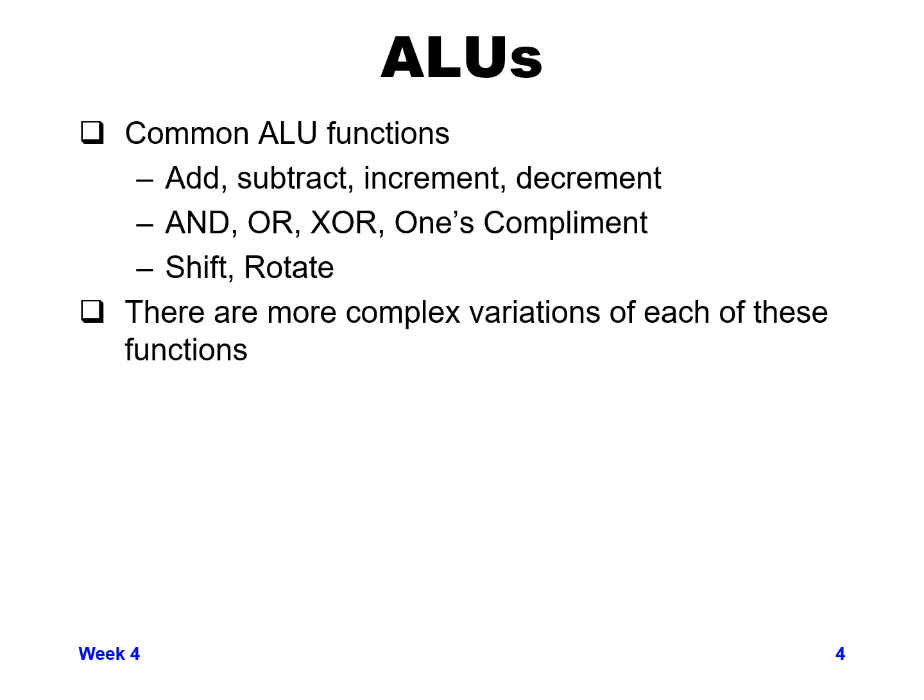And then there's other functions like shift and rotate, where you will take either the value of A or B and shift all the bits left or right, or basically rotate it around. So with a shift, you'll shift in a value either on the left or right, depending on if you're shifting left or right. With a rotate, you would take the value from one end as it's rotating or shifting out and rotate it back in to the other end. And then there's other more complex variations of each of these functions, but we'll just go into some of the basic functions today.